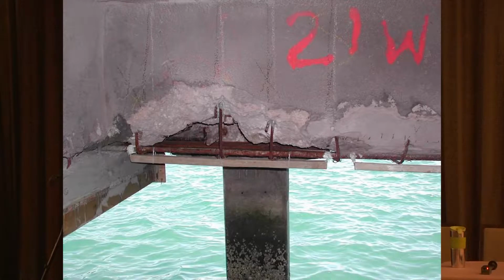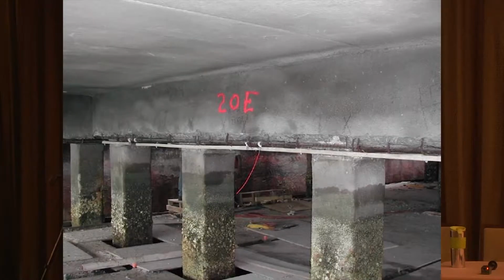And here's a marine application. This is a slightly different version. Instead of that tubular version, this one looks kind of like a 2x4. It's a slightly different technology, but it has the capability of providing current either wet or dry in a saltwater environment. And this has 2 pounds of zinc per lineal foot. It's a lot of zinc overall. And then here again, this is that same system being placed in a pile cap right there.